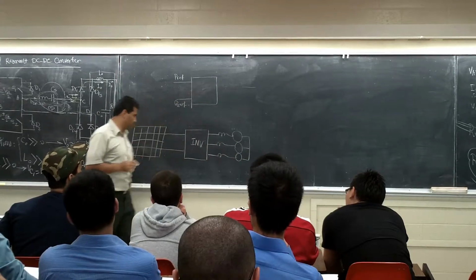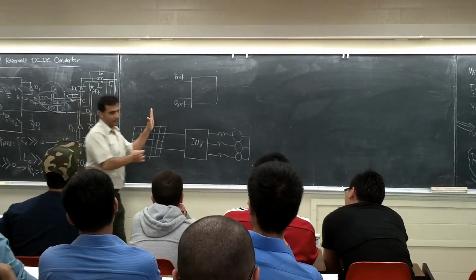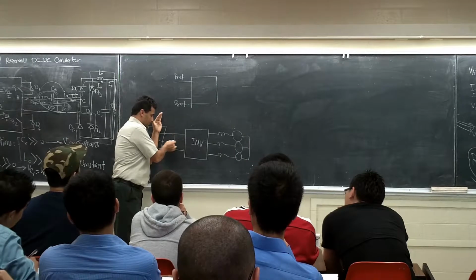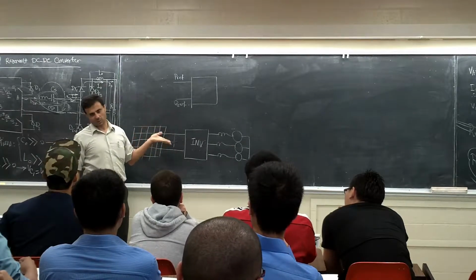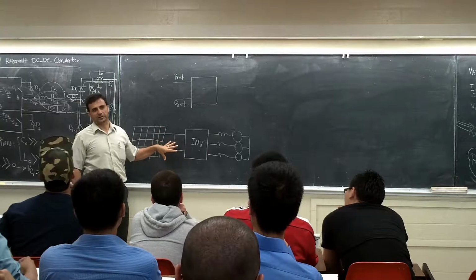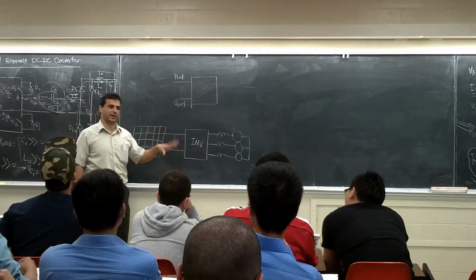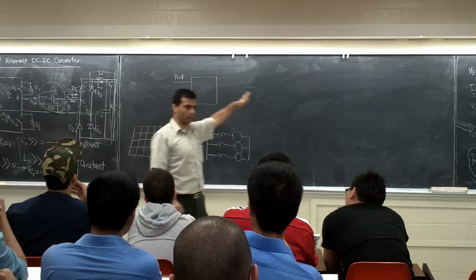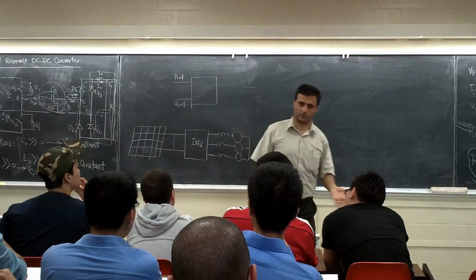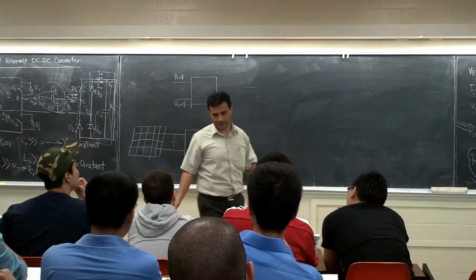Right? This is what we have. Previously, we had a battery here. What was the advantage of the battery? We don't care about this DC plus anymore. It's fixed, right? The battery voltage is going to change, but it's not sudden. It's going to be, for example, full charge 600 volt, come down to, for example, 500 volt. It still is kind of fixed, when you look at it.